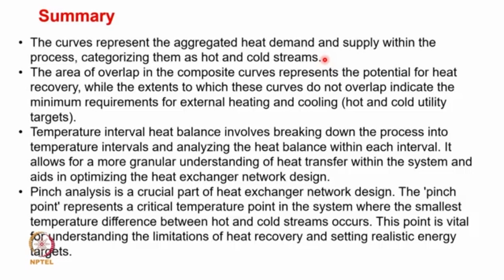Okay, so just to summarize our study, the curves that represent aggregated heat demand and heat supply within the process are categorized as hot and cold streams. The area of overlap of the composite curves represents the potential for heat recovery, while the extent to which the curves do not overlap indicates the minimum requirement of external heating.